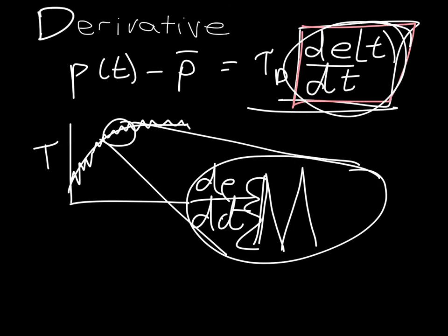So for practical control, derivative control is always used in conjunction with some other control mode. Truth be told, that's the same for PI control as well. The integrating action is usually combined with proportional action. But even more so for derivative, you will very seldom see something like a pure D controller. You will typically only see a PID controller.